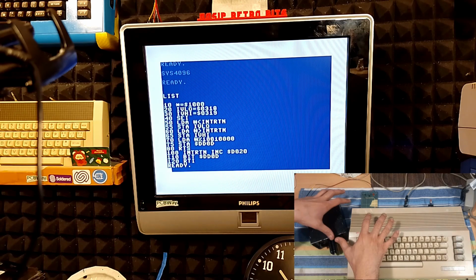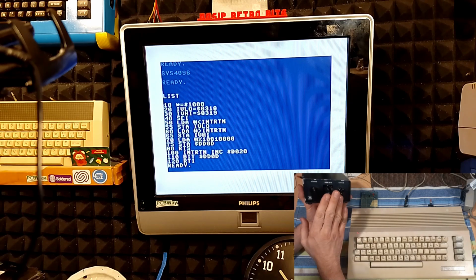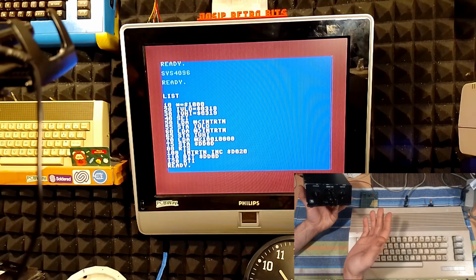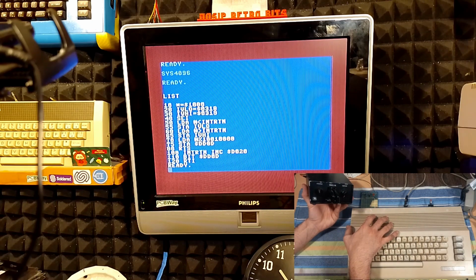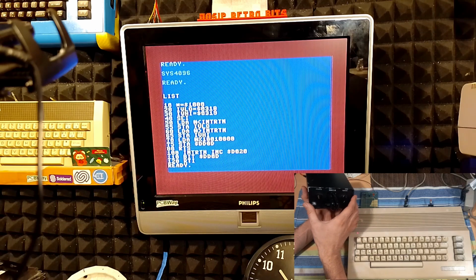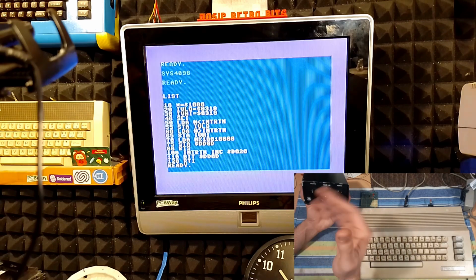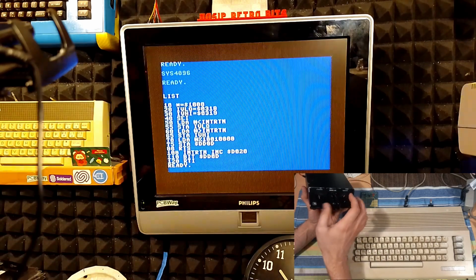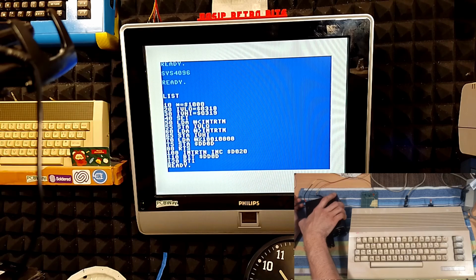And now, once we are able to detect the high signal from our Morse code keyer with the external interrupt, once we enter our interrupt routine, we can now start to monitor the PB0 pin and try to measure how long the signal is going to be high and try to determine whether it's dot or dash. Yeah, let's do that.